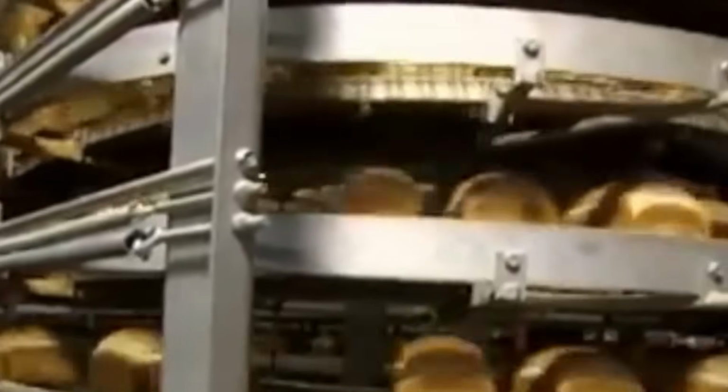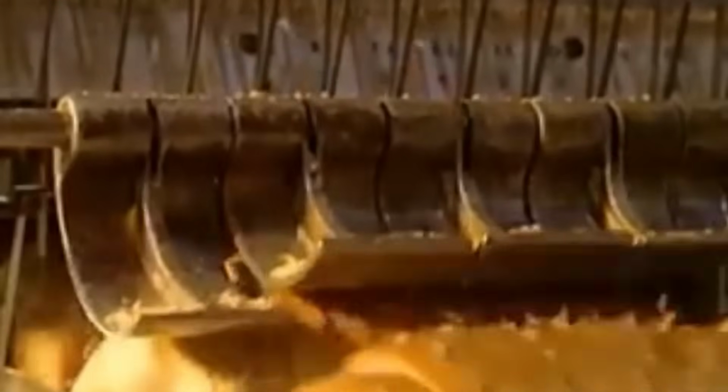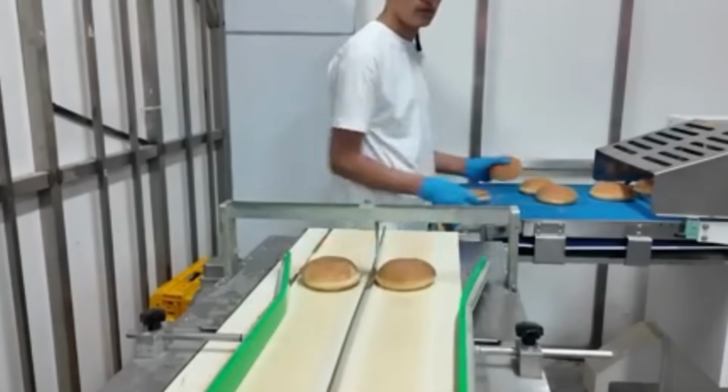If the bread is destined for sale as whole loaves, it bypasses this stage, but most continue on to the slicer. This machine is built for speed. Multiple blades, mounted vertically in a row, oscillate at high speed as each loaf is pushed through by a belt-driven ram. The slices fall into alignment instantly, held together by guide rails as they move forward still in loaf shape.